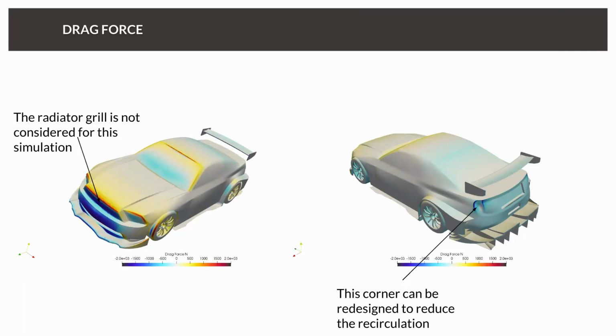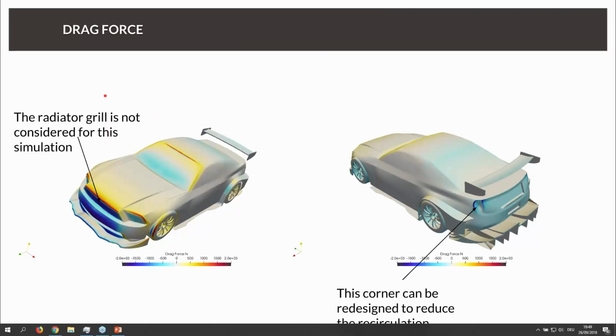So in this case, be careful. Blue means it's creating drag, and red means it's creating a force working in the opposite direction of drag. And this is just theory. So in theory, you could say that your windshield and your engine bay are reducing the drag, but that's not necessarily a valid interpretation, because they're just creating this force for very small parts. However, you can see it like that.